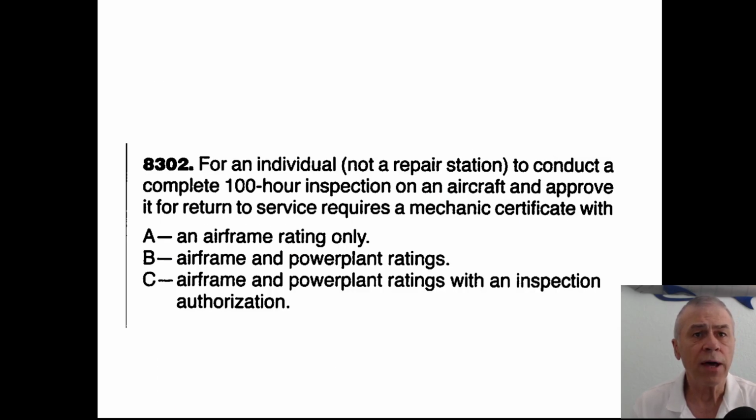Question: for an individual, not a repair station, to conduct a complete 100-hour inspection on an aircraft and approve it for return to service requires a mechanic certificate with, do you just need an airframe? No, that makes me look at the question again. It does say a 100-hour inspection on an aircraft. When they use aircraft, that's a little broader than airframe. So if you were going to go with A, I would look for the airframe word in the top part. Since they say aircraft, that could include the engine and or the propeller.